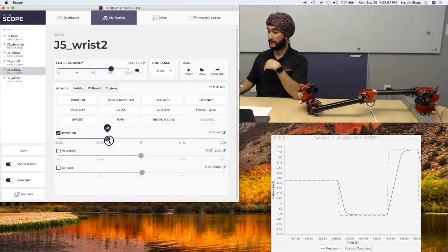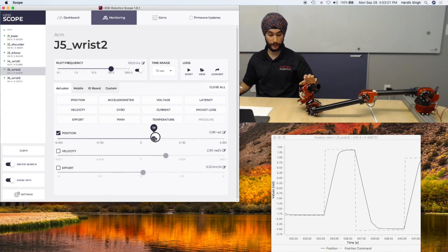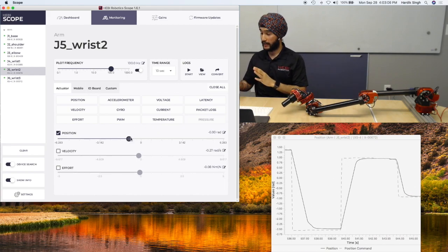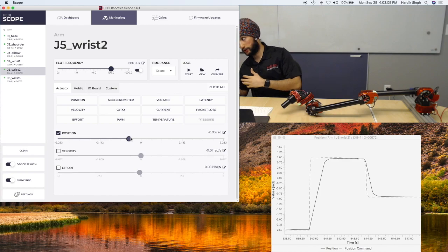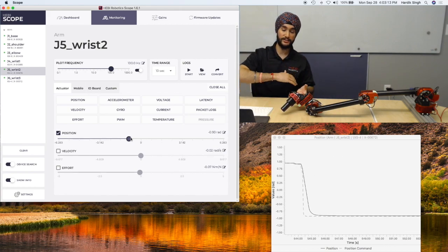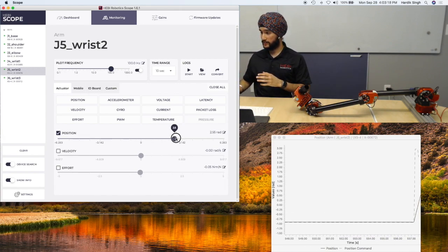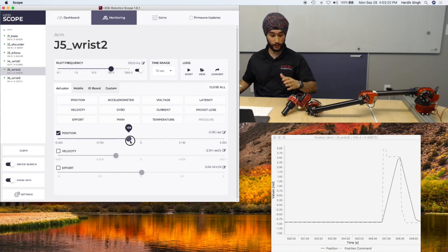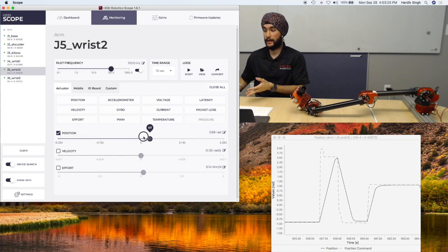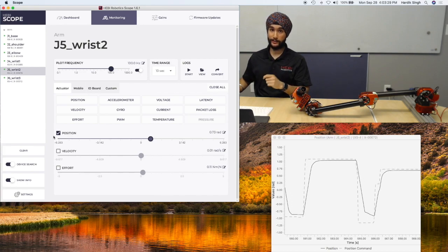What it's doing is trying to get there as fast as possible, and at the end, smoothing out the motion of the actuator. That's actually coded into our firmware, so that's already happening. But that comes down to our control strategy. Our control strategy is making sure that when a position is commanded, we're going to approach that position and smoothen out the profile of our motion a little bit. But what we're seeing here is that if I wanted to get smooth motion for this joint, this degree of freedom, I'm not getting that by commanding just position values. How I can get it, however, is using trajectories.